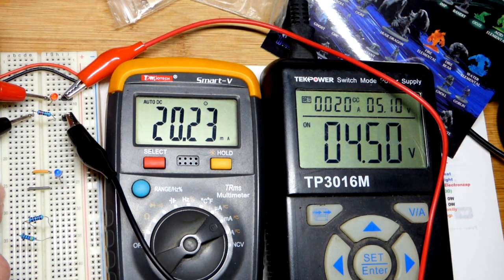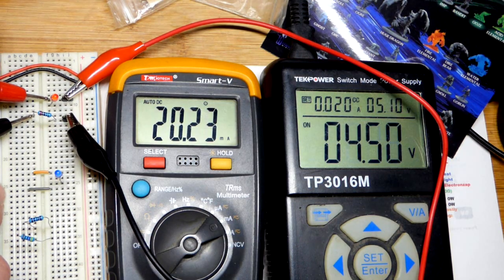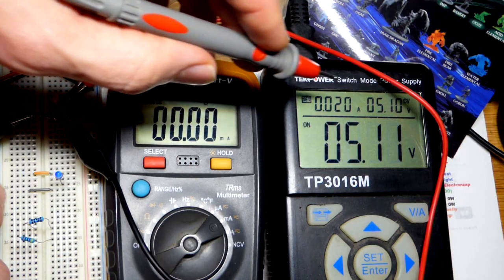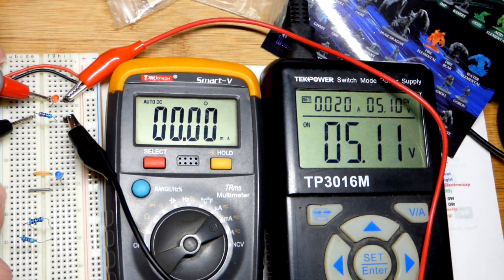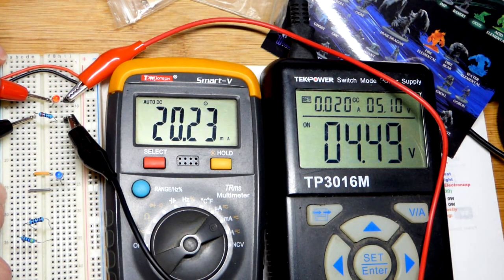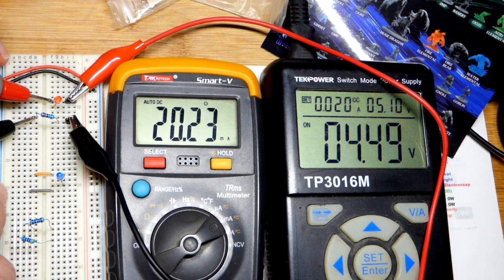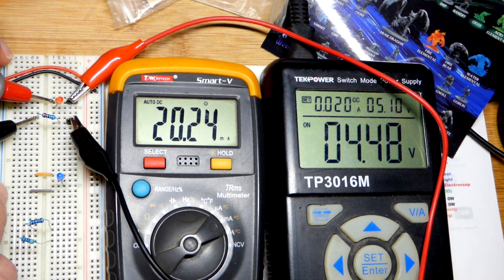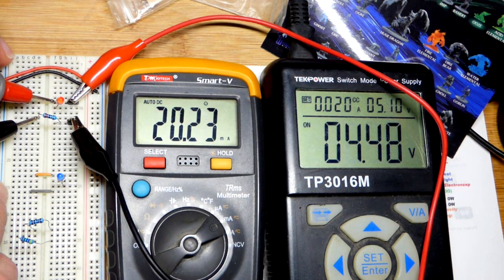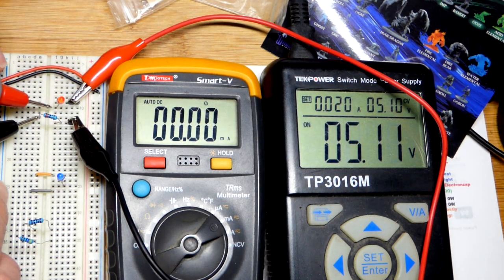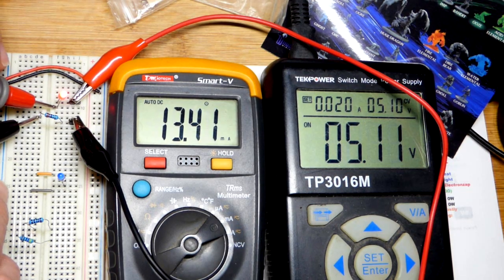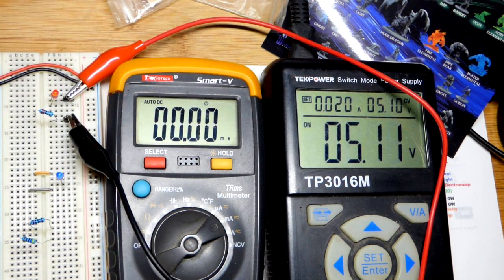You can see next to the 20 milliamps up there, 0.02 amps, there's a little CC popping up right there. That's telling me it's constant current. Now the power supply is setting a current, not a voltage. And generally, unless you're purposely using the power supply to set a current, you don't want it setting a current. You just want it setting the voltage, and the load will take care of the current, like we got right there, how much current is flowing. And so that's another way to troubleshoot.